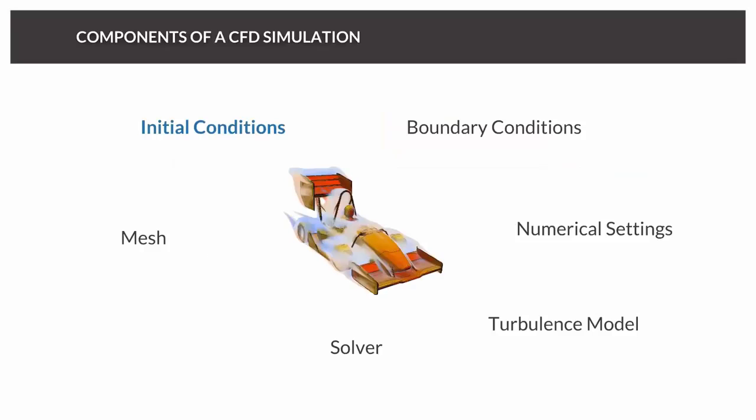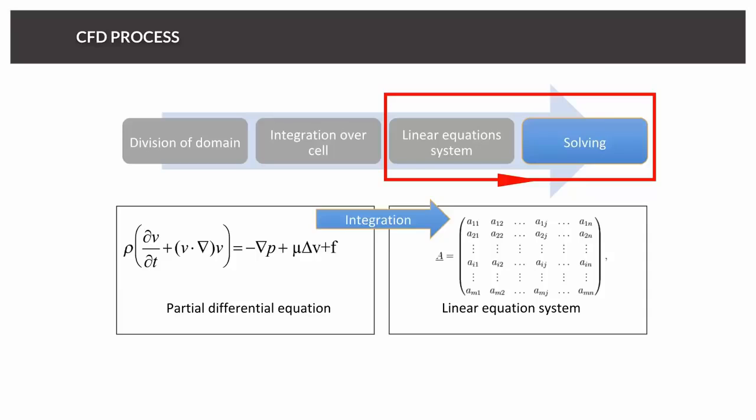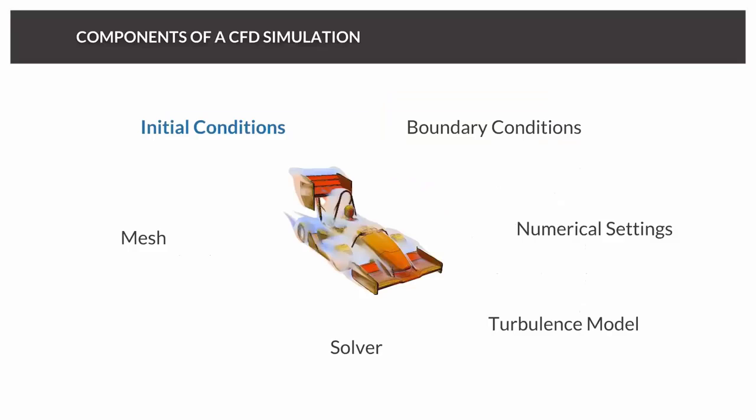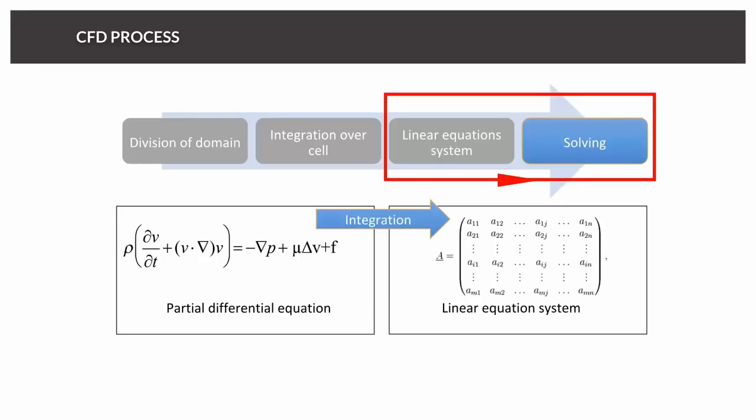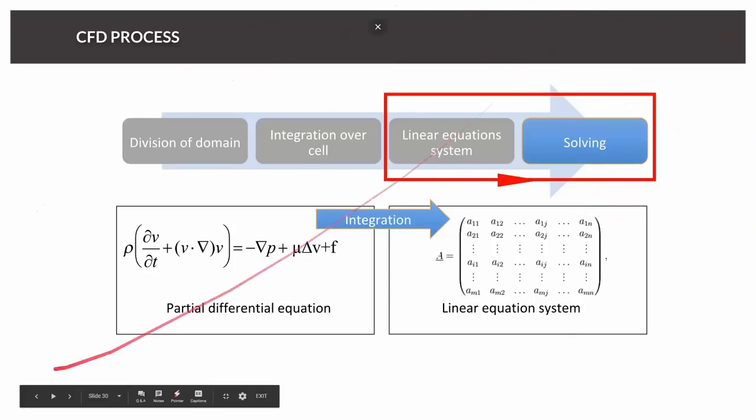And these initial conditions, or initial values, or initial state, are not the most important aspect. And I could talk for hours about it, but let's make it simple. If you take a look at this from a hands-on perspective, initial conditions, usually you never need to touch them. And it's like this: the nearer your initial conditions are to the solution, the faster your simulation will converge. So this process of iteration will become shorter. But it's not very easy to find the right initial conditions.